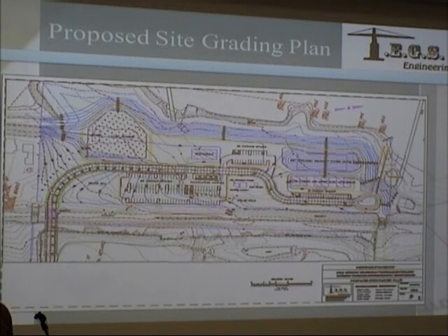So for grading, we had a 4% slope wrapping around the boundary of our site and also in the retaining pond. And for ADA requirements for our lawn seating over here, we had a slope less than 5% to accommodate people to sit and watch performances on the stage.